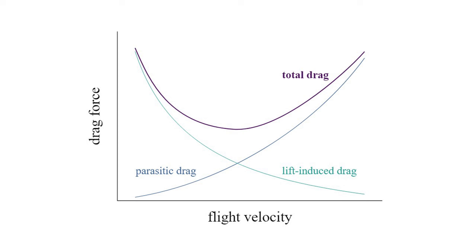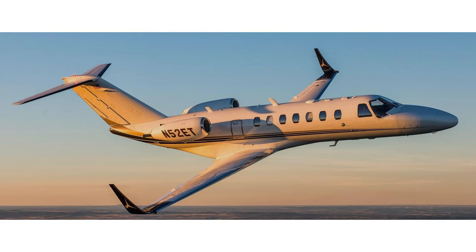Remember that the profile drag increases with velocity while the induced drag decreases, so this is where good engineering judgment and analysis is needed to determine the optimal operating window for winglet design. Proper optimization will result in the greatest reduction in induced drag for the smallest increase in profile drag. This optimal point can be considered a crossover point. Below this crossover airspeed, the winglets provide a performance advantage, but above it, the additional wetted area generates enough profile drag to decrease the overall performance and outweigh the advantages that you gain with the winglet.